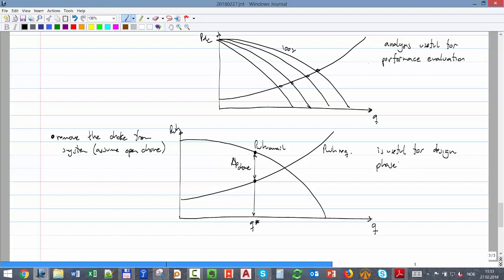Also, what happens if I want to produce a rate which is higher than the equilibrium rate? Can I do it? No? Are you sure? Let's say I want to produce a rate that is here. That's the equilibrium rate, then that's the rate with the choke. But let's say I want to produce more. For some reason, my economical rate, I found this field will not fly unless I produce this rate minimum. I made my NPV calculation and I say at least I have to produce that rate for it to be profitable. Change tubing size, decide.